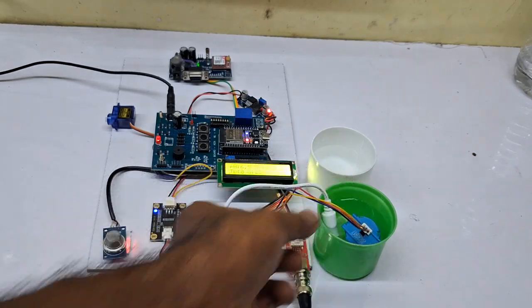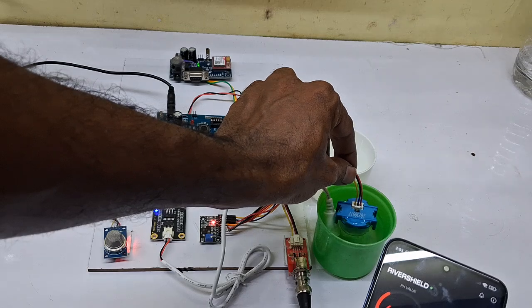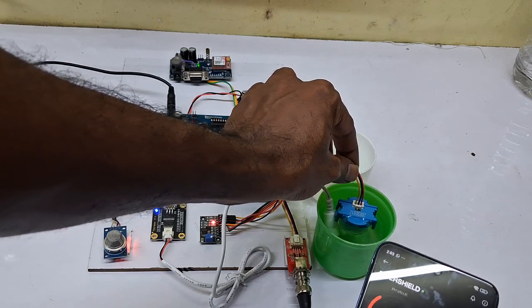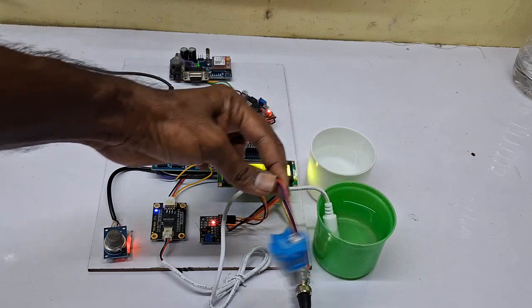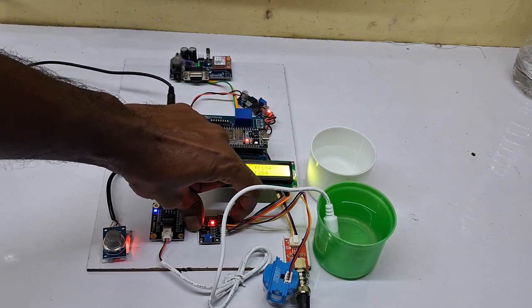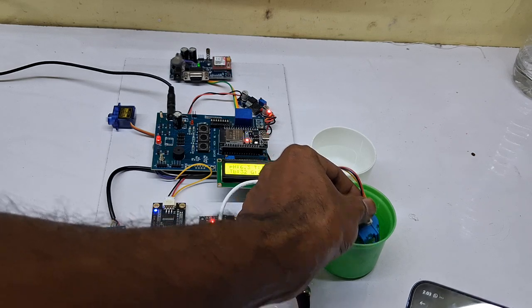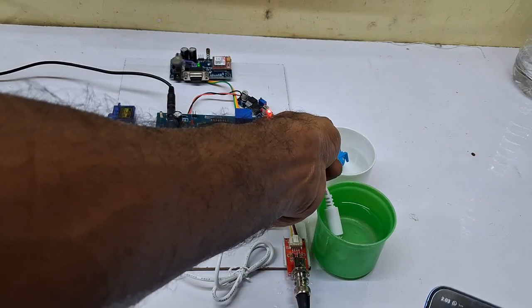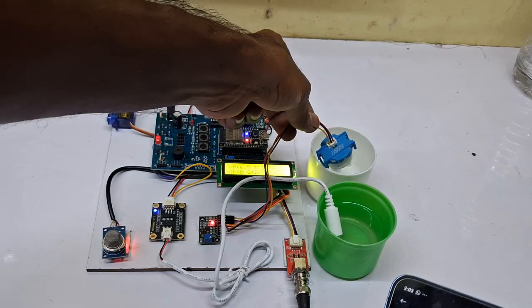And finally we are using a turbidity sensor also, in order to monitor the turbidity value of the water. If we put it inside the water, we can get the turbidity value. So this is the turbidity. Now it's showing turbidity is 0. We have to fix a loose contact. Okay, so turbidity is 32. The turbidity is almost similar because we are using a transparent solution in both cases. That's why it's showing a constant value.